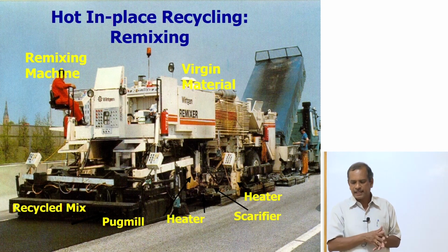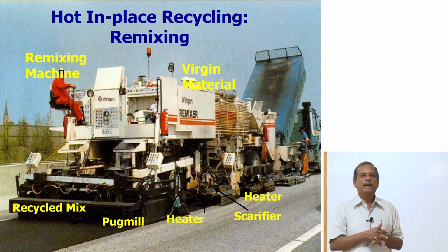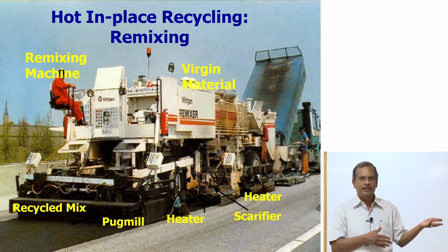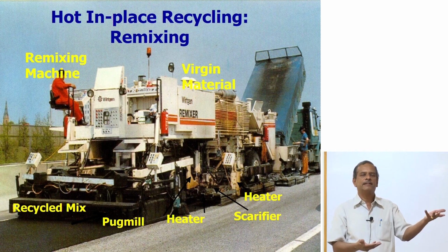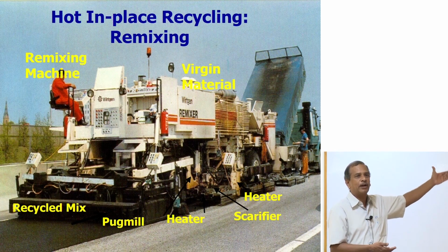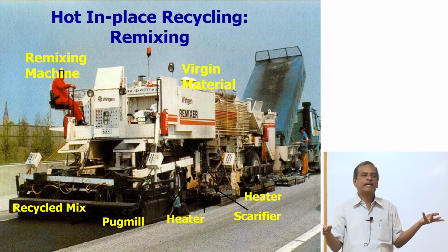So the technologies that have to be adopted in the years to come are, number one, you have to reduce the construction, either by stabilizing the subgrade, using geocells, geogrids, geosynthetics, using modified binders, or in the case of recycling, adopt white topping, or recycle the material, either hot recycling or cold recycling. Any of the technologies can be adopted.